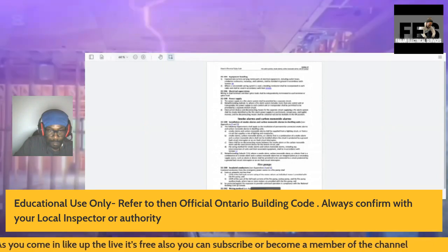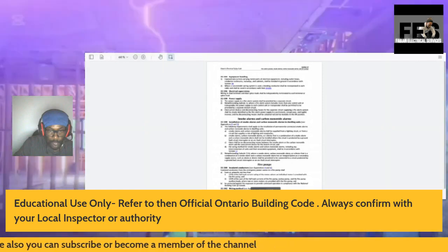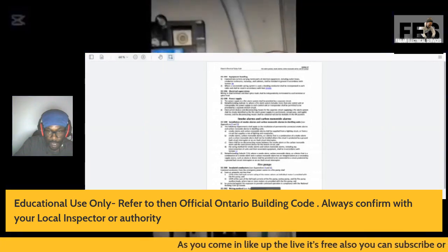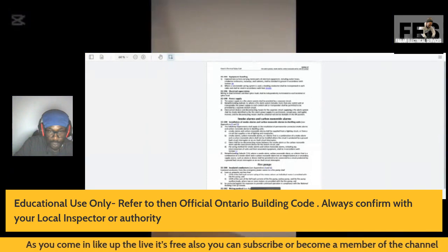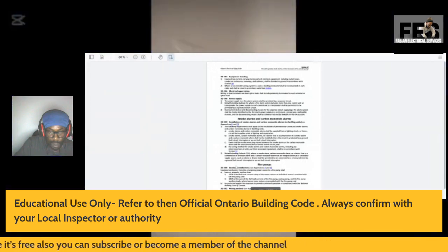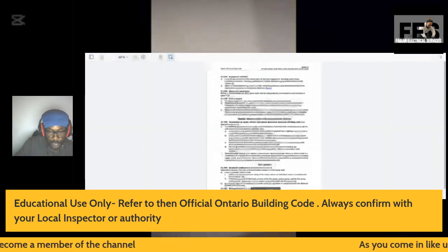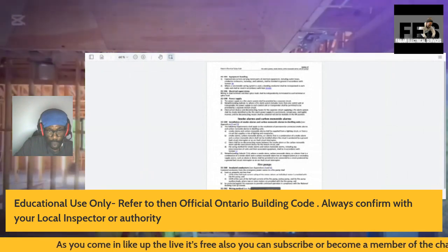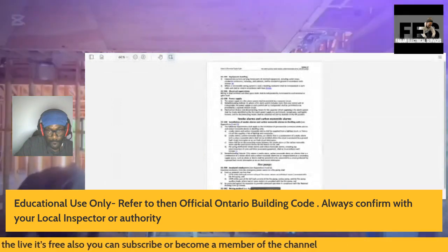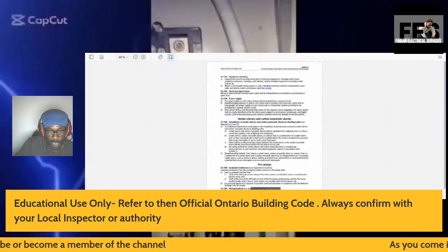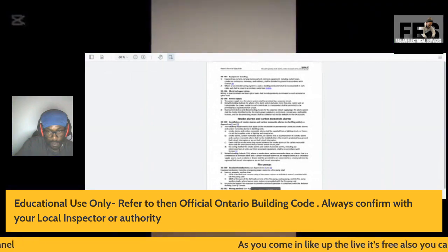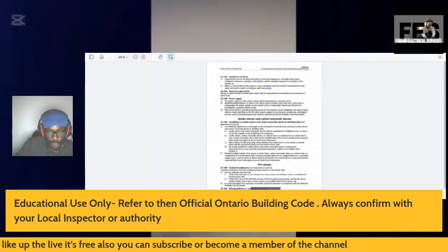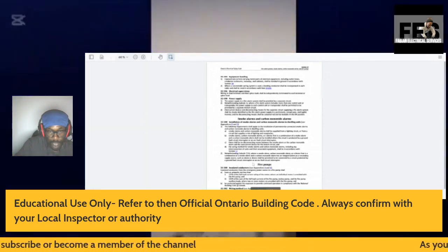Notwithstanding Sub-Rule 1B, where a smoke alarm, carbon monoxide alarm, or a device that is a combination of a smoke alarm and a carbon monoxide alarm has an integral battery as a secondary supply source, such an alarm or device shall be permitted to be connected to a circuit protected by a ground fault circuit interrupter or an arc fault circuit interrupter.